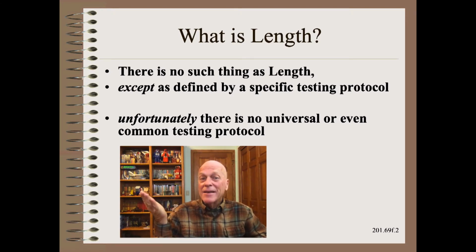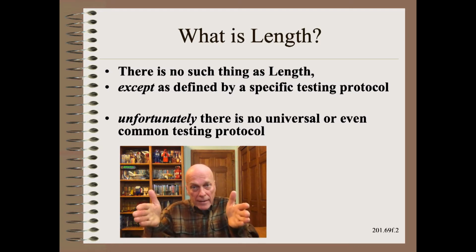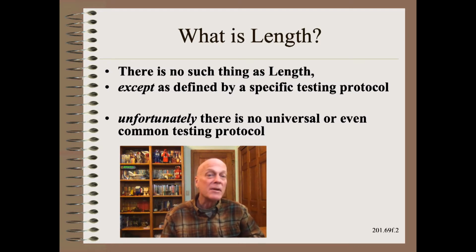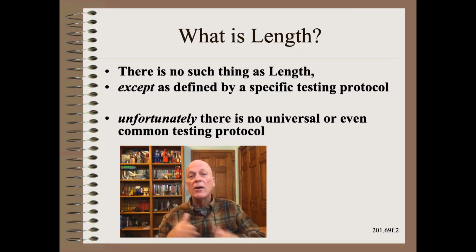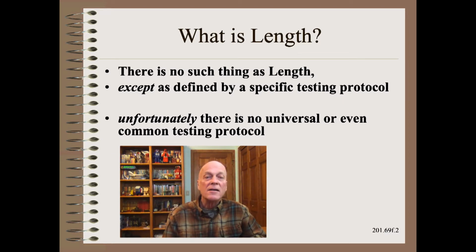So, what is length? Recall from our last clip, Web20169f, that there is no such thing as width except as defined by a specific test protocol. It is even worse for roll length. There is no test standard or even a near universal practice. Thus, when and where and how you and your customer measure length will all affect the values that you each get. Differences in the detail of how you and your customer each measure length can result in customer-supplier disputes.